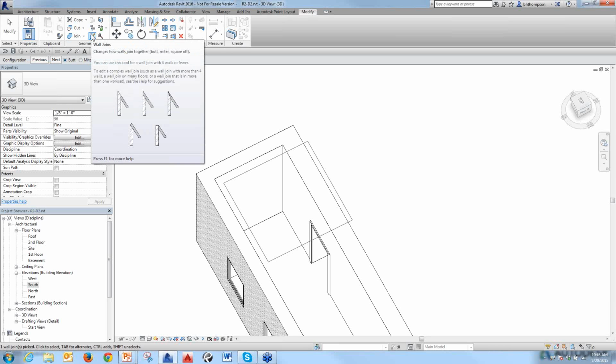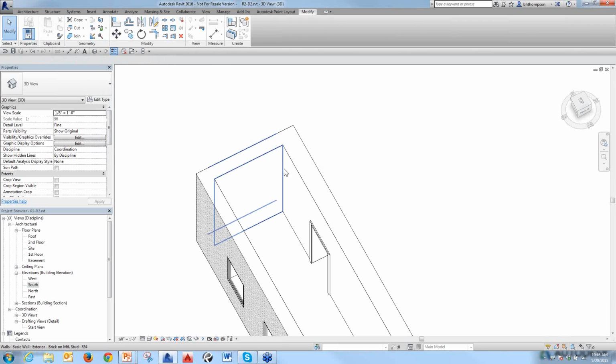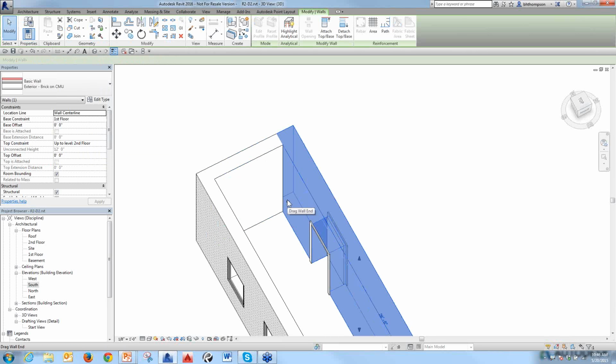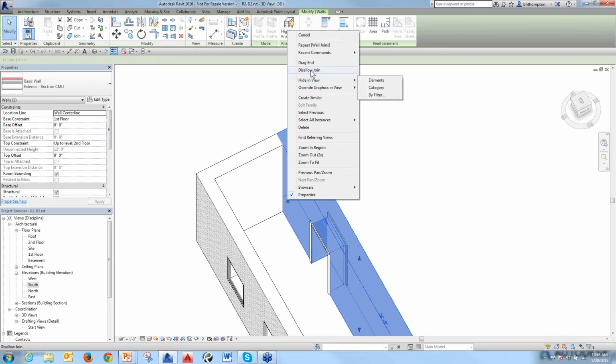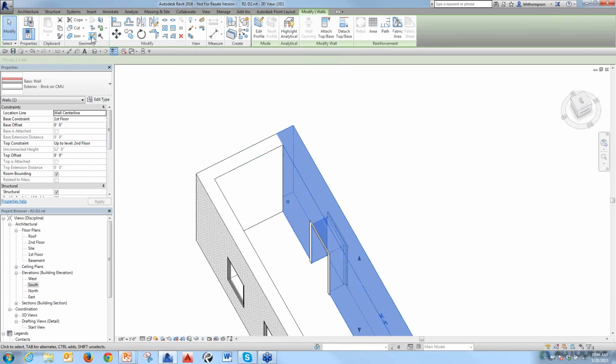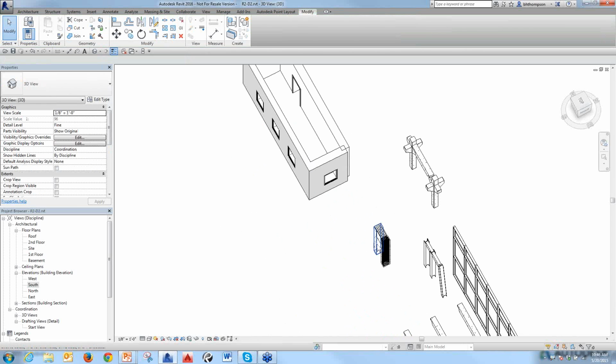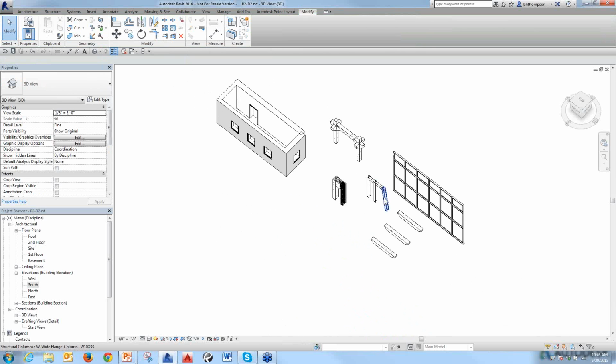You have seen that in Revit Radio if you guys are paying attention, but if you aren't, you now can go in there and do the wall joints. You no longer have to do the mystical right click on the dot and say disallow joint to get that done. You can also do that right within the wall cleanups, which I thought was a really cool one. Because right-clicking on that dot had to be obvious to everybody. Yeah. Oh yeah, you could always find it.